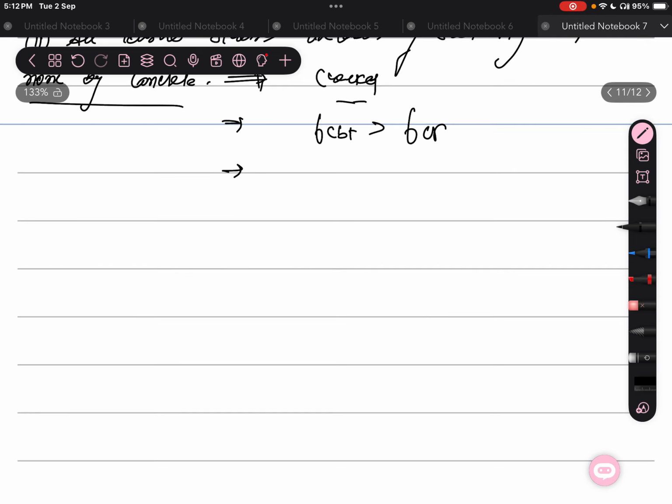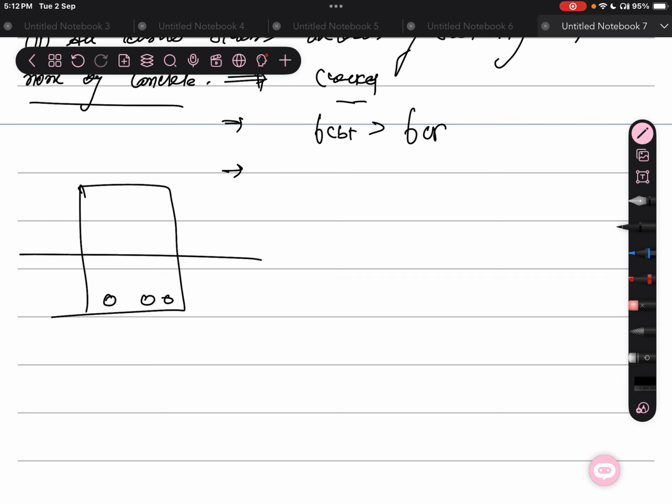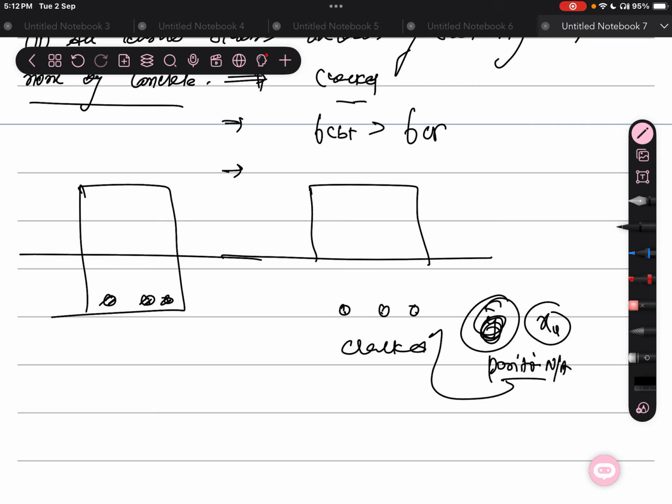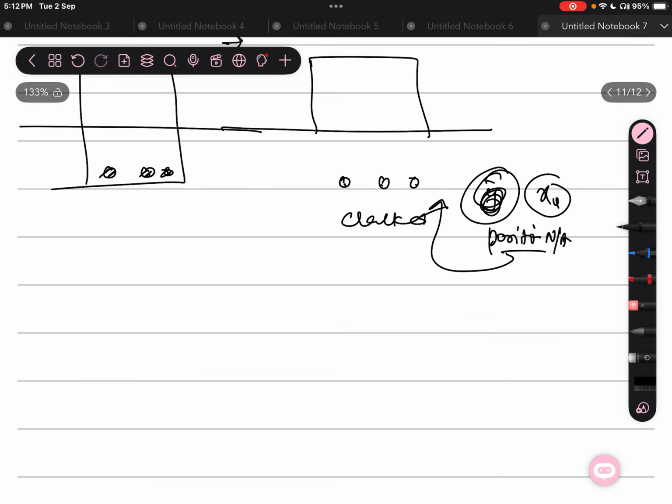Like this is the concrete side, so we'll neglect the tension side, and only steel will be there. This is in case of the cracked section. Similarly, y bar, or we can say xu, the position of the neutral axis, will be calculated like this. We'll take only the steel side, and that will transfer on the steel side. This is in case of cracked.